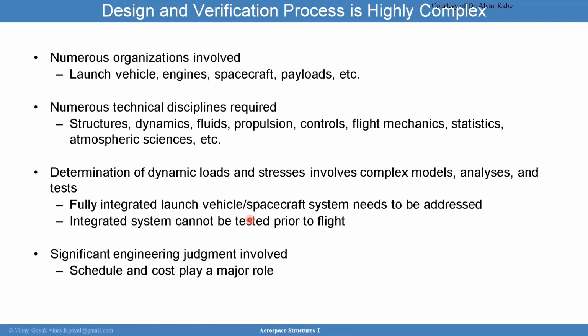Well, yes, it is related because if the dynamic environments were significantly high, that could pose a problem for those manufacturing issues you may have encountered. For example, an impact damage event on the composite structure could cause part of the composite structure to debond. And so now you have an initiation point for failure that now needs to be considered in the context of the dynamic loads a launch vehicle may experience.